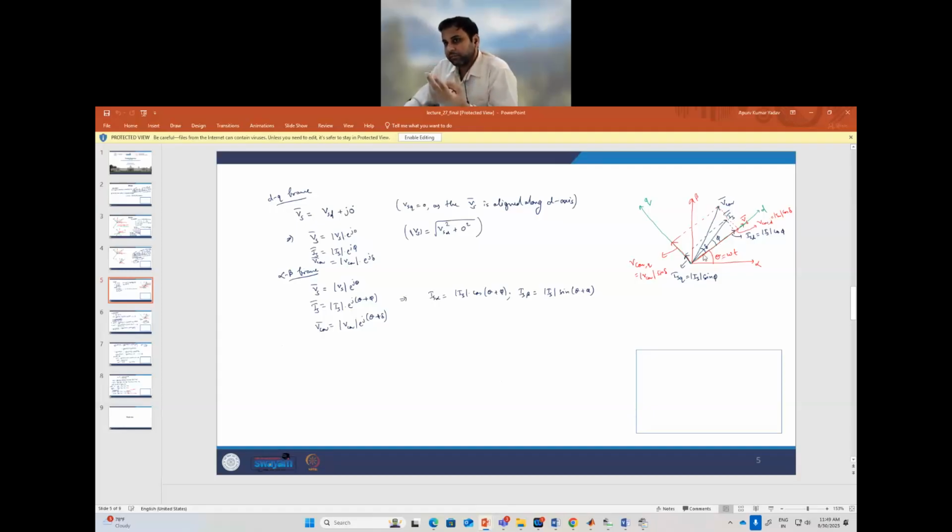There are two things happening with this vector. One is, obviously, we are changing the magnitude of the vector to control the current going through the inductor. At the same time, we are also controlling the angle of that vector. So you have to take down the angle as well as the magnitude information. That is why, if you write in terms of alpha beta and then go to dq, you will have that angle information intact with you.